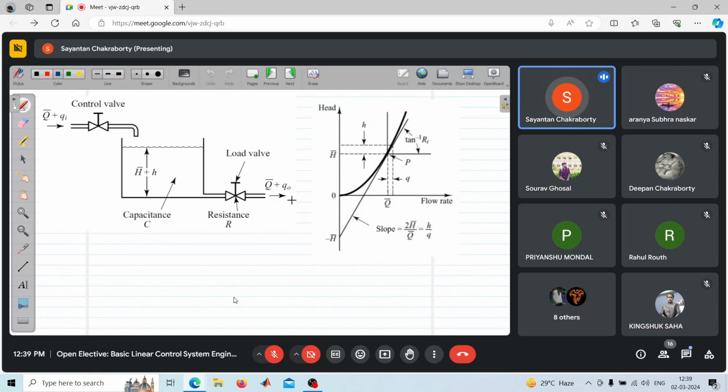Now, how do you obtain that? Before we start, we should make one thing clear: in analyzing a system that involves fluid flow, we first have to determine the flow regime. There are basically two types of flow regime, laminar flow and turbulent flow, and this is determined by the magnitude of the Reynolds number.